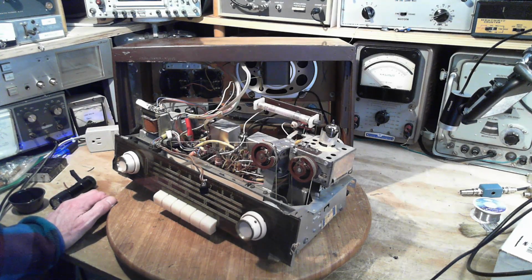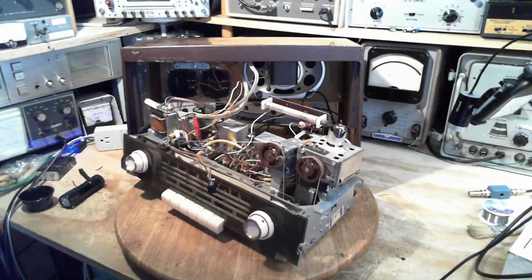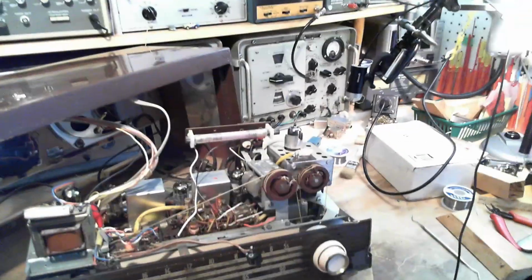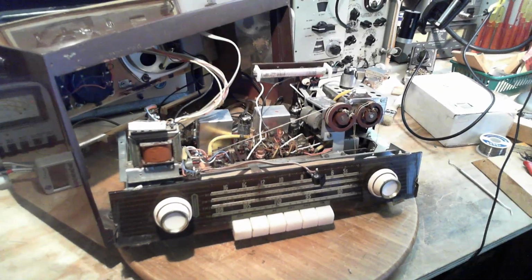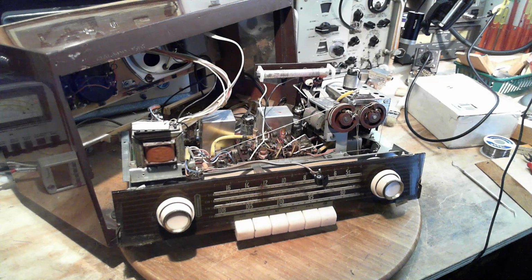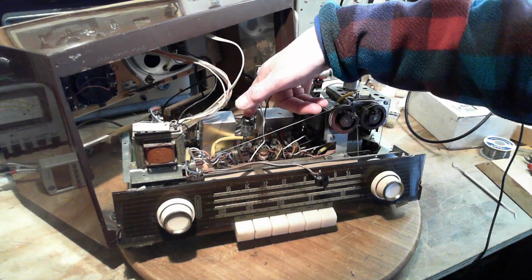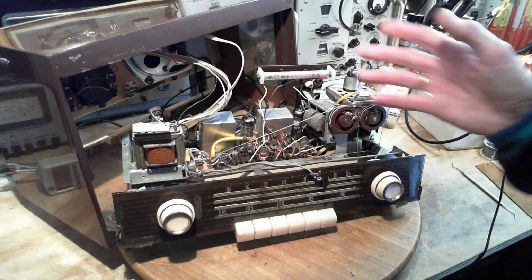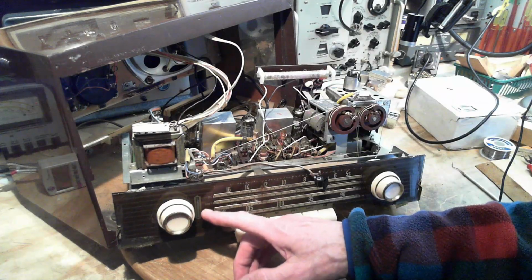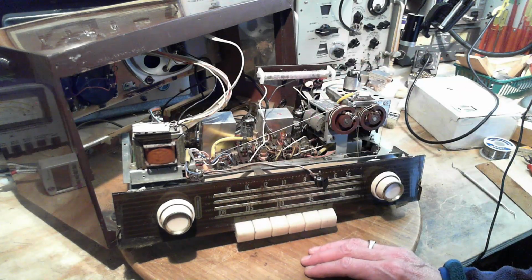So the impression I get from this is the AVC voltage is not being applied to some of the tubes, probably these two tubes here that are being affected by the AVC grid bias voltage, and they're not being affected. So this means that the gain of these tubes remains high even with a strong signal, and the result is far too much volume coming out of the radio, and an overlap, or the eye staying closed or even overlapping. And I would think the fuzziness is probably part of the picture too in some way.